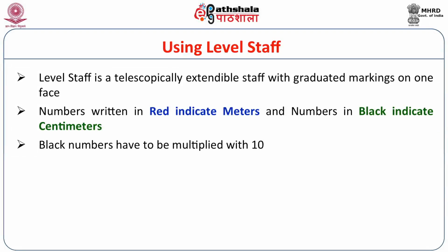That means if you see 2 in black, then that means it is indicating 20 centimeters. So, we have to use this method, or we have to remember this while taking the measurements. For the survey, the field assistant has to hold the survey pole exactly above the nodes that are marked using the field markers, which are also attached with the node number.